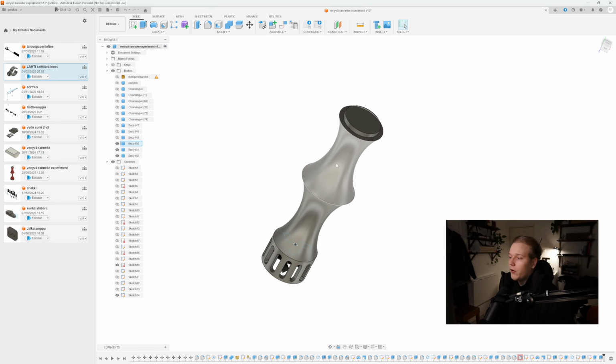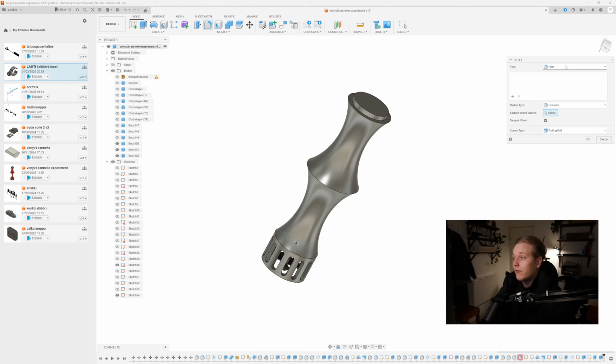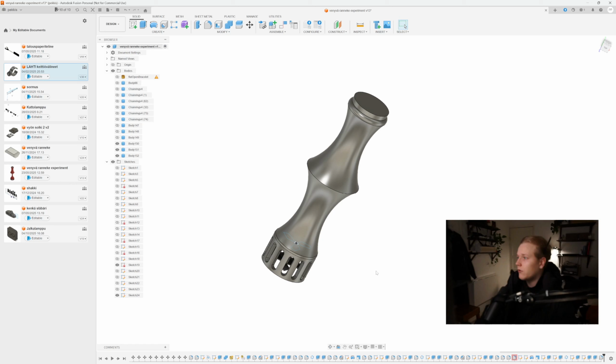Now we are at a point where we have all the rough components, all the measurements of the part we're modeling, but it's really rough. It doesn't have the colors. So now we're gonna start doing some filleting and chamfering. A fillet is basically gonna round off the edge, and we can apply it to a lot of the edges here. You can do like a 3mm fillet, or maybe 4. 4 seems good.